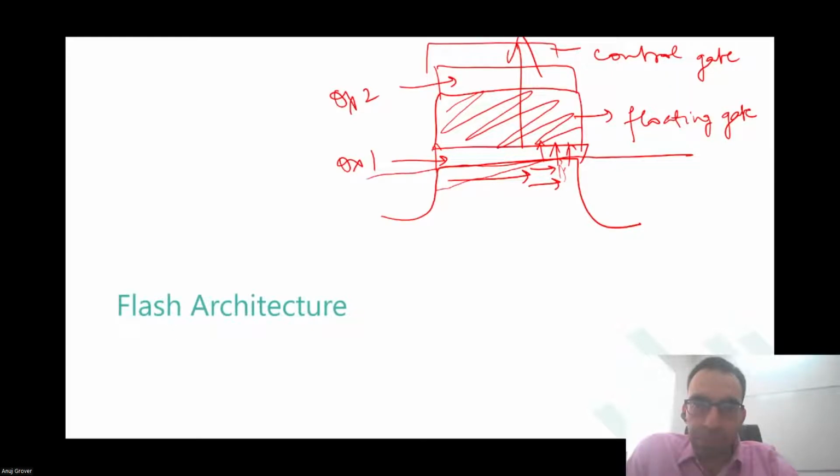Yes, sir. So can we just say that in hot carrier injection the VT is always increasing? You can say that, yes. Because you start to talk about hot carriers only when you're talking about an inversion layer being there and charges moving at very high speed, having a lot of kinetic energy. Yes, sir. So HCI will always lead to an increase in VT.